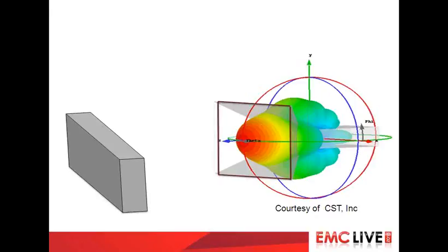However, now she gives us that in one hand, now she takes it from the other hand. The reflective power has now become a bit of a problem, because, as you can see there, there's a good chance that if it's a large EUT with a beautifully screened front panel, as we would design into it, because we don't want impinging RF to get into our system, a lot of it could well be bounced straight back into the aperture, and the amplifier will see it. Thank you, Mother Nature.